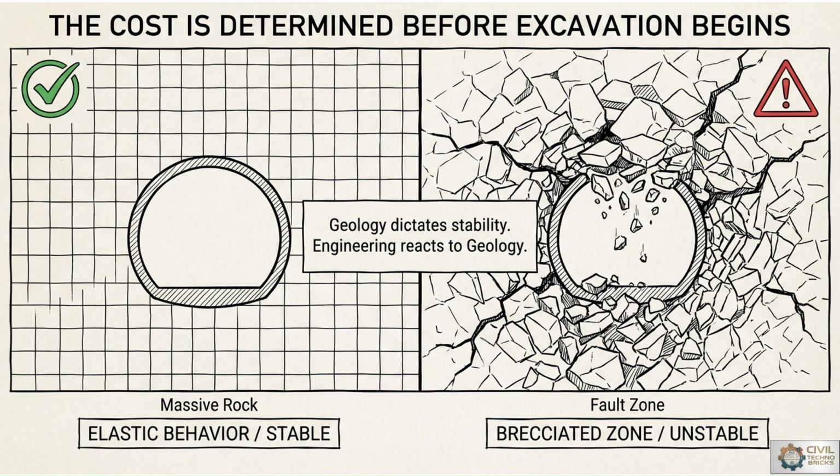So selection of tunnel alignment, which is the most important role of the civil engineer, depends on terrain, topographical characteristics, rock competency, fault zones, and environmental conditions too. Proper geological assessment improves tunnel design, support system, and long-term structural performance.